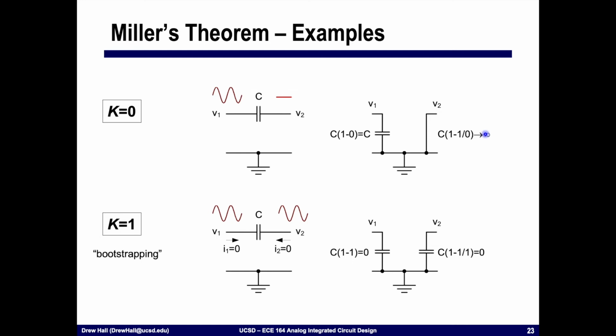All right, so now let's work through the case when the gain is equal to positive 1. I wiggle the input. The output is now copying exactly what I'm applying at the input. So think about putting a voltage follower below this. The input and the output are identical.